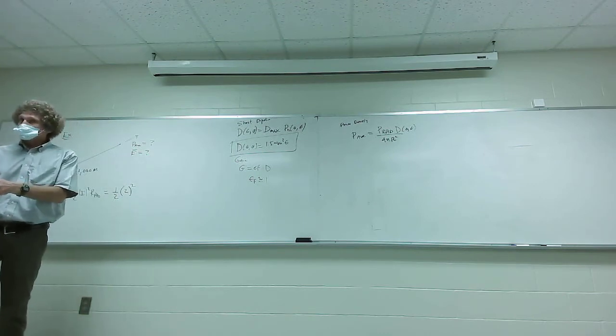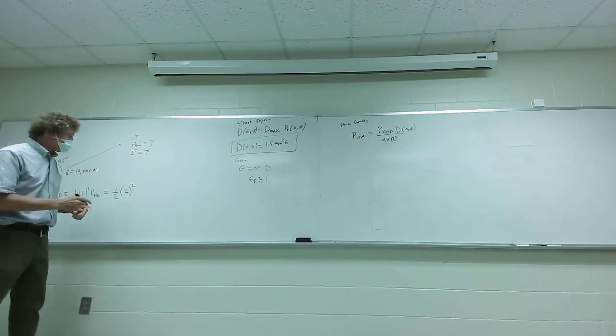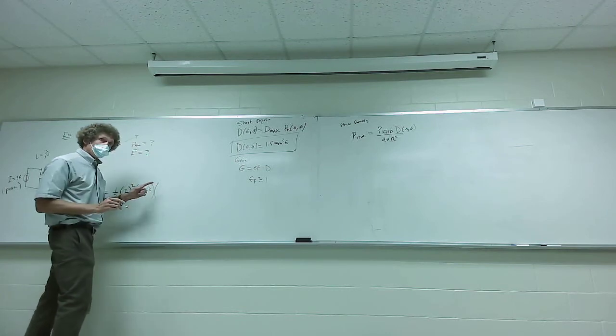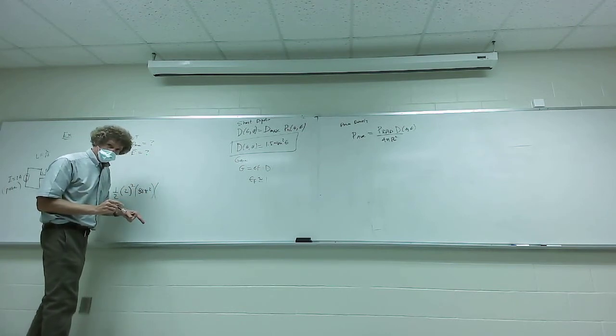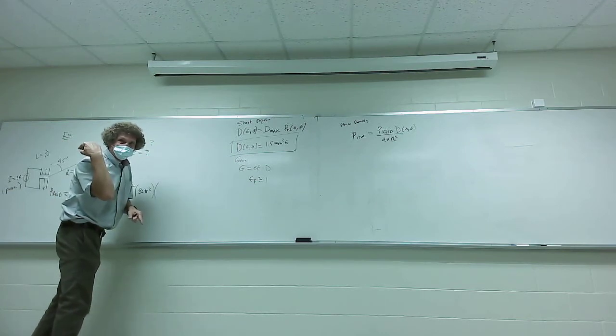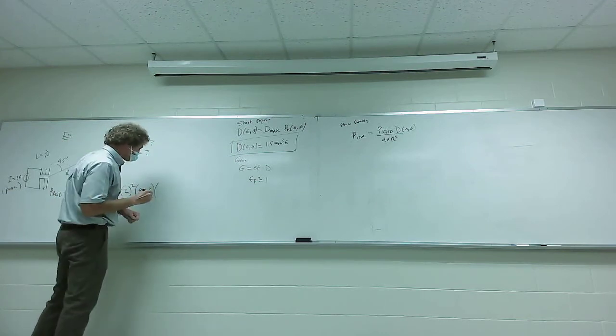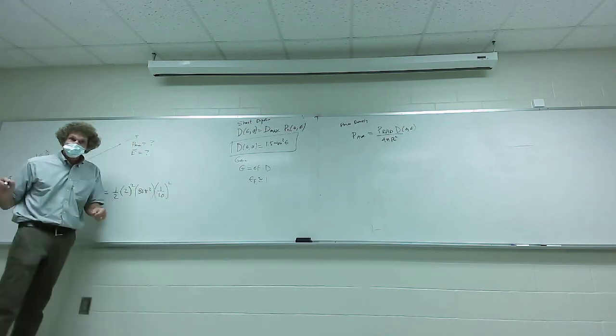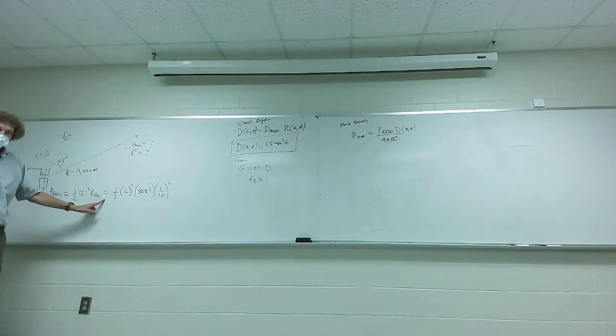No, I'll give that to you. R rad for a short dipole is 80 pi squared times (L over lambda) squared, right? L over lambda is what? Take a look. Simply 1/10, squared, right? Y'all with me? So we've got P rad.